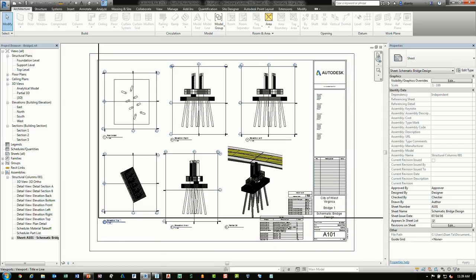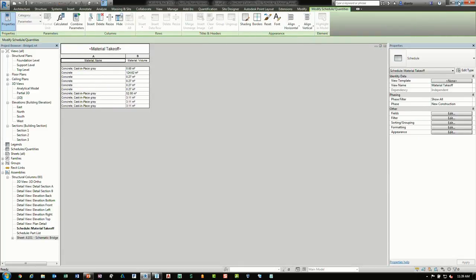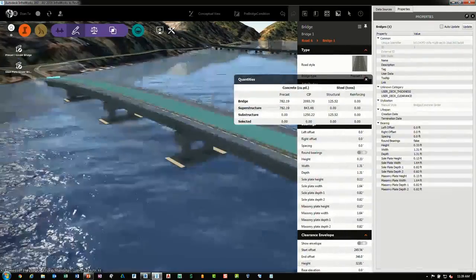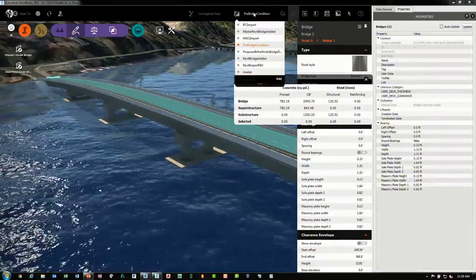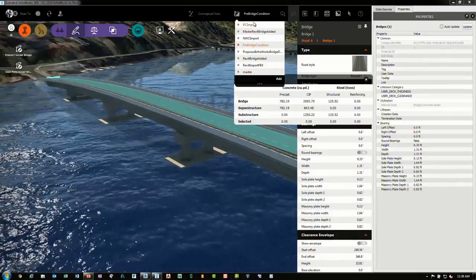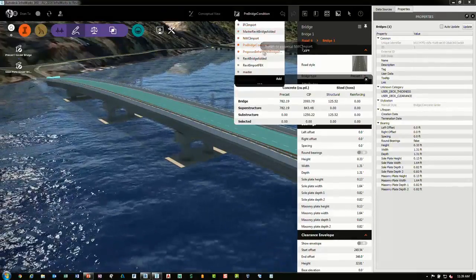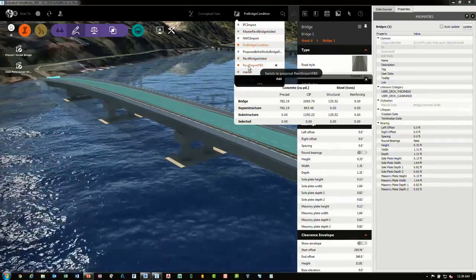How do we take the Revit information that we've massaged and adjusted and bring it back into InfraWorks? Let's head over back into InfraWorks. And I'll show you, I created several proposals for different ways to bring it in. IFC import, NWC import, the Revit being added as a default, and then even FBX.